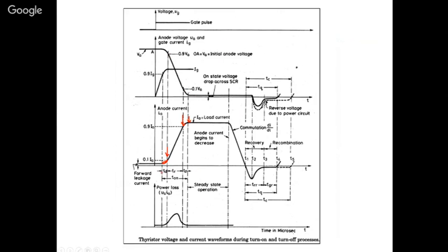So this overall together is nothing but your turn on. But in turn on, you have to just remember, during this rise time, you can see there is more power loss. So this we cannot do anything about. The rise time depends on the manufacturer, but you can look in the data sheet to see whether the rise time is more or not, and accordingly you can choose a device. When the rise time is less, it is better, there will be less power loss.